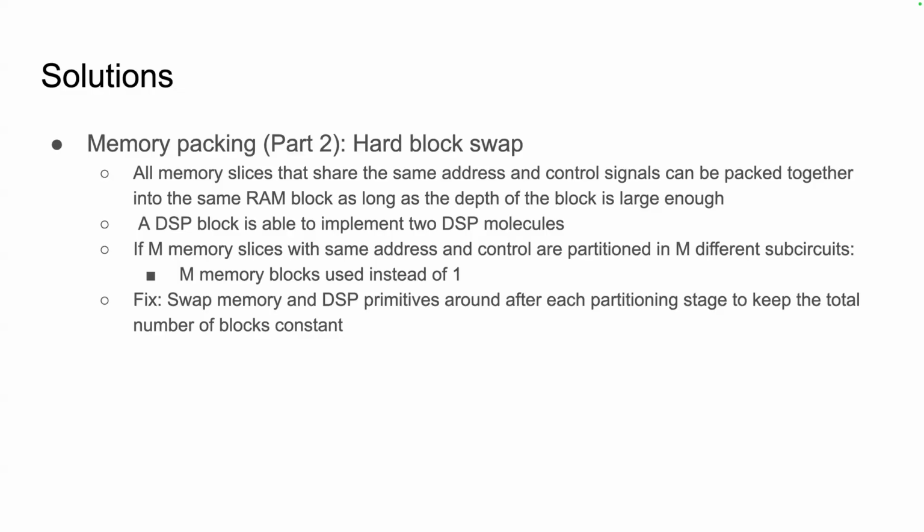So actually, the number of things you put in depends on what you're trying to stick in there. And then the way Quartus represents this is with a mac mult primitive, which is the multiplier, and then a mac out that represents everything else, like an accumulator after. So those get tied together. And if you're doing something like a 36x36 one, you'll get,